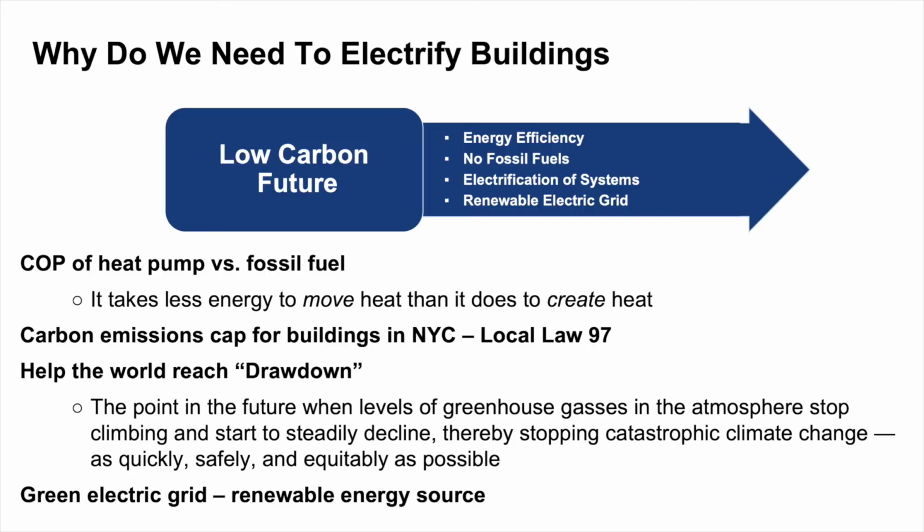Now, a heat pump is a means by which to electrify buildings, but why are we talking about this at all? Why do we need to electrify buildings? There are four main drivers that are really pushing us to this conversation that is at the forefront of our industry here. Number one, efficiency. It simply takes less energy to move heat than it does to create heat. Matt introduced us to the first and second law of thermodynamics. It just takes less power. Instead of burning a fossil fuel to make that new energy, why don't we harness the energy we already have in place to move that heat transfer medium around?